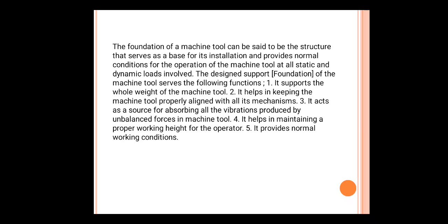The foundation can be said to be the structure that serves as a base for its installation and provides normal conditions for the operation of the machine tool under all static and dynamic loads involved. The designed support of the machine tool serves the following functions. Which are those functions? We'll see here. First, it supports the whole weight of the machine tool.